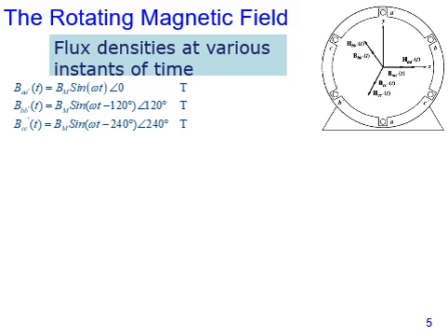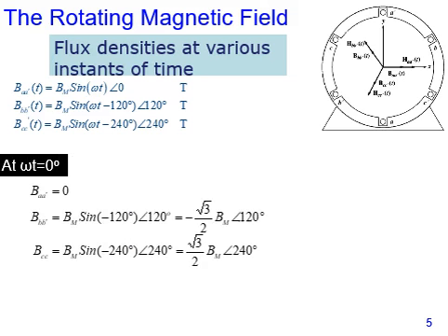The rotating magnetic field, as we discussed previously, we will calculate this magnetic field at different angles, at different omega t. So if we put omega t equal to 0 in this equation, we will get sine 0, and after getting sine 0, the whole right hand side would become 0, as you have seen in the first equation for B AA bar.